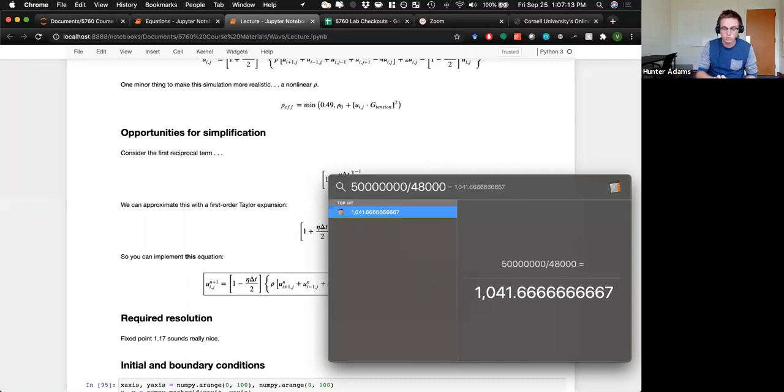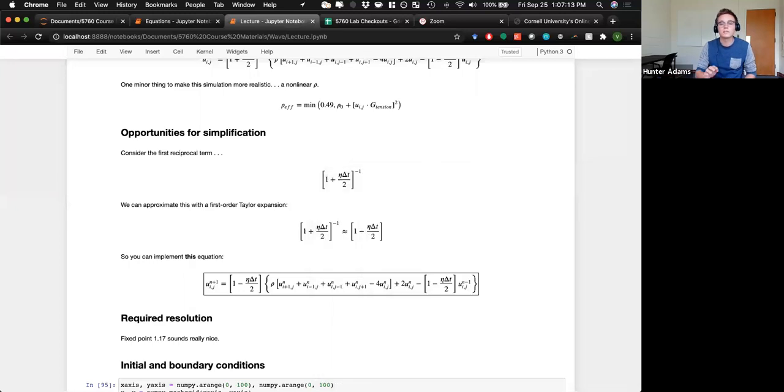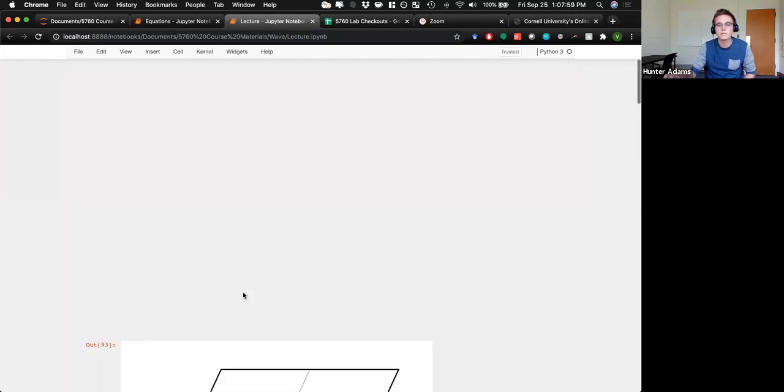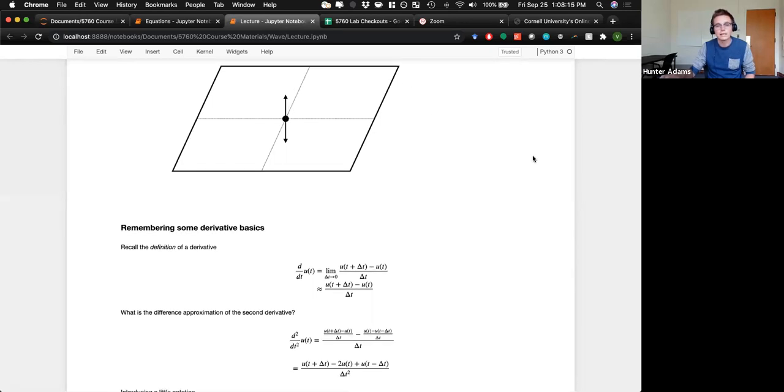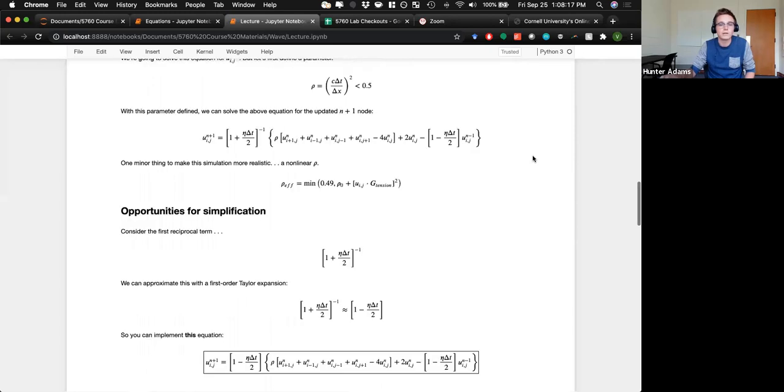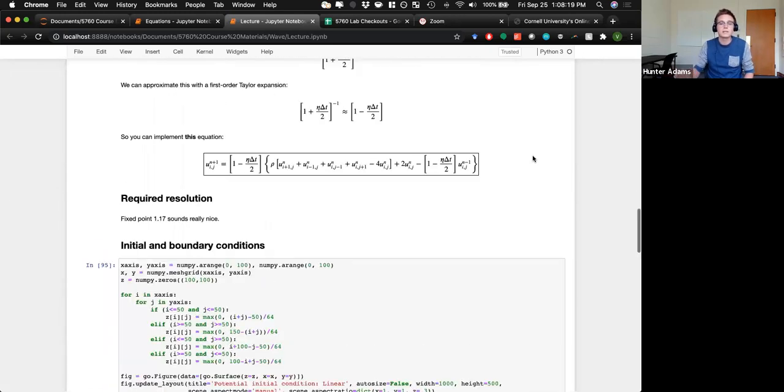So if you were to do the simplest version of parallelization, which is to say, if you were to take your state machine for updating a single node like this one and make a bunch of copies of it and update them all in parallel and then wait for the next audio sample before you update them again, you could update each of these nodes in parallel in 2 to 5 cycles of the FPGA, which means the FPGA would be sitting doing nothing for over 99% of the time.